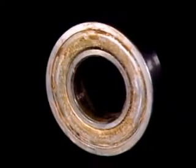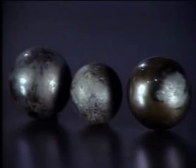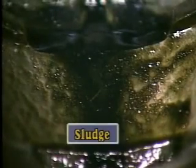Besides forming acids, lubricant oxidation can form harmful deposits on metal surfaces. The varnish deposits on this bearing came from oxidized grease. More severe oxidation produces carbon deposits. Both varnish and carbon deposits can greatly increase friction on bearings and other machine parts and keep them from operating freely. Carbon deposits can also collect in lubricants and form sludge.